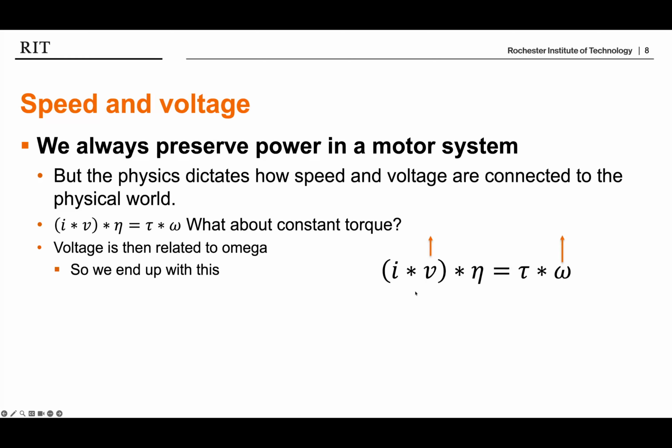And again, there is a theoretical maximum here. The sort of nerdy thought is that as that coil of wire inside my motor, when it's not energized, spins past a magnet or a magnet moves past it, that creates some voltage that goes back into our system. This is how a generator works. And in the case of a motor, this acts as almost an electric brake. So there is this physical threshold by design of every motor. It has to exist that limits the amount of speed of that motor based on its voltage.